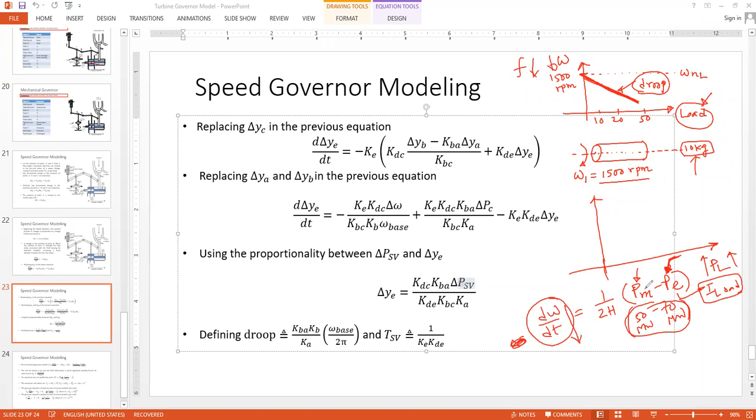So the speed, until and unless we are putting more steam, if it's a steam turbine, steam generator scheme, if we are not providing any further input through the PM, then this speed will slowly fall down. The rotor speed will fall like this. So if we require more power, P load, the speed of the rotor is expected to fall continuously as you are increasing the demand.